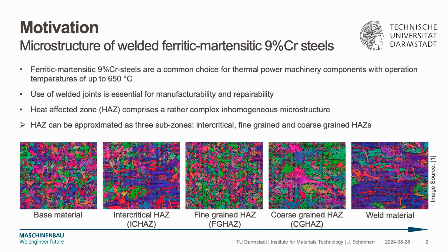And next to the base material, there's an intercritical heat-affected zone. This heat-affected zone consists of partly dissolved microstructure and over-tempered martensite.